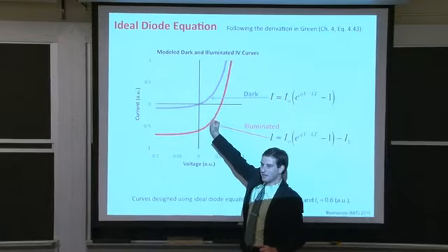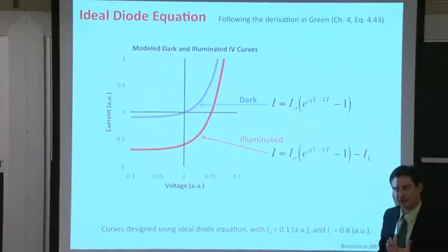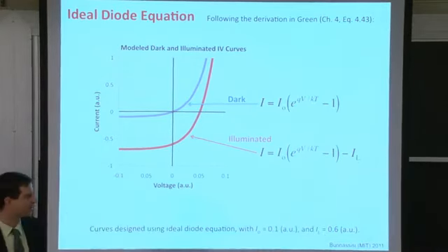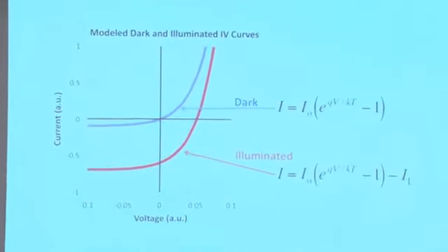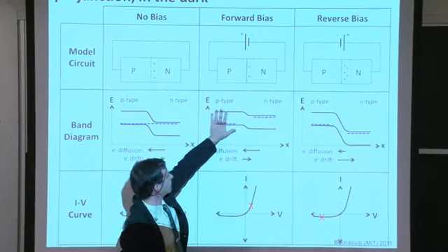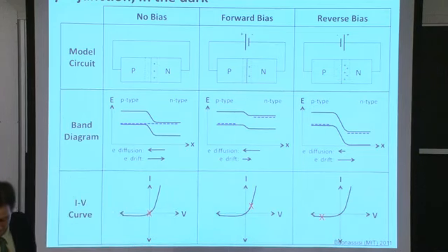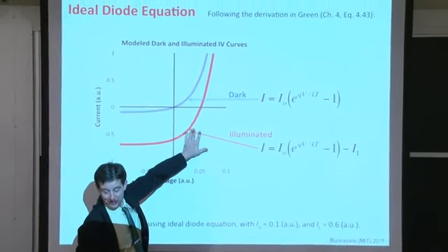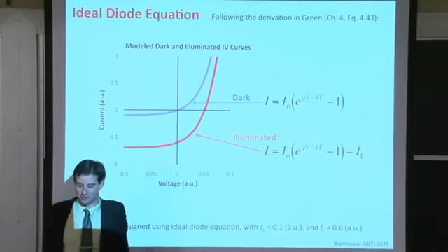So we're beginning to develop an intuitive understanding of where electrons are flowing inside of our solar cells, in the dark and under illumination. The dark is important because we can test our devices in the dark, and we can still learn a lot about our solar cell device characteristics. As well, under forward bias conditions in the dark, we can force carriers from one side of the junction to the other the wrong way and probe for weaknesses in the p-n junction region, so that's helpful. In the illumination condition, obviously, we're testing the total amount of power that's coming out of our device. So again, this is very useful because it's off of this red curve here that we define the efficiency or the performance of the solar cell.